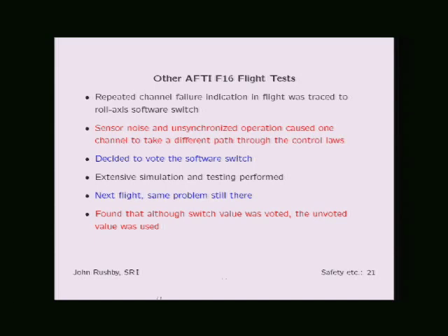So one of the things that you see here is that first of all, you have to have some fault tolerance system to deal with faults in the field. That's a given. But all of these instances are cases where they actually had a fault tolerance subsystem. They had some software dealing with faults, and that software had a bug in it, or was not correctly designed. So you have to be really careful about designing the right fault tolerance solution. If you have a checker in your system, you have to check the checker and make sure that's correct. You can't just assume that's going to be okay.